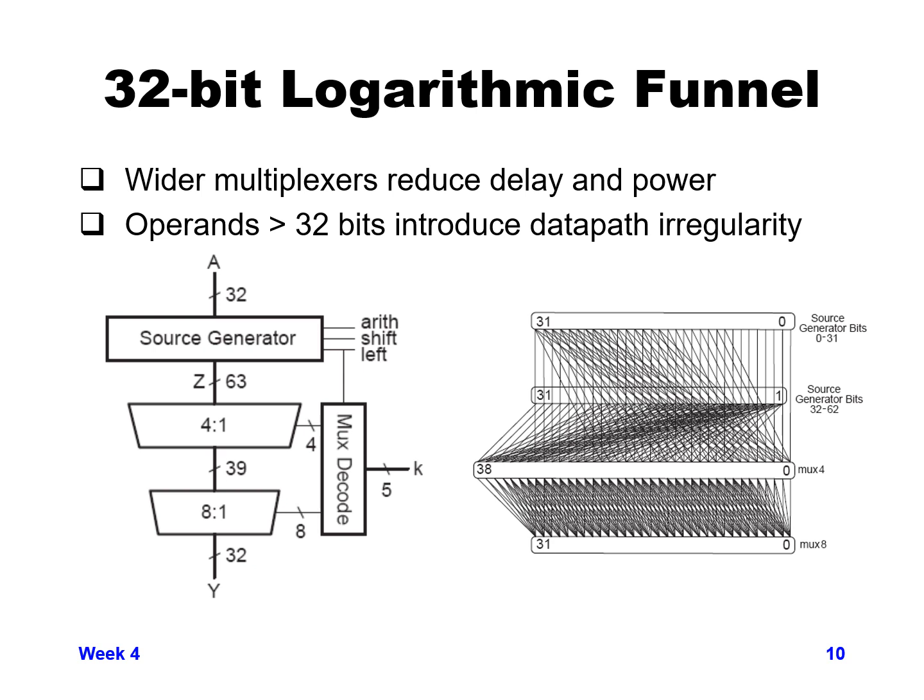Then we can send those bits in the connections that we need by multiples of 8 to the MUX4. The MUX4 is going to need 8 additional bits, because depending on whether we're rotating right or left, we're going to have an additional 8 bits going off to one side or the other. And then when we do our final shift for the 8-to-1 MUX, shifting 0 through 7, we wind up with a final 32-bit number coming out at the end.